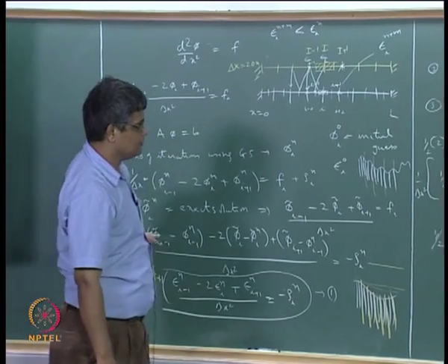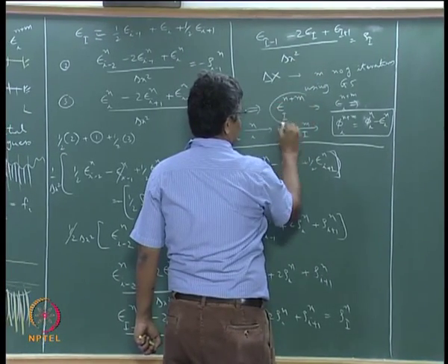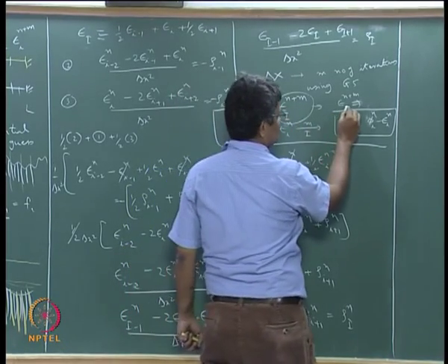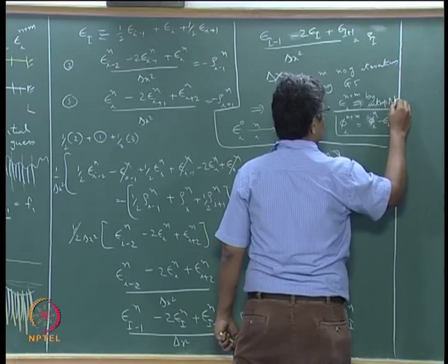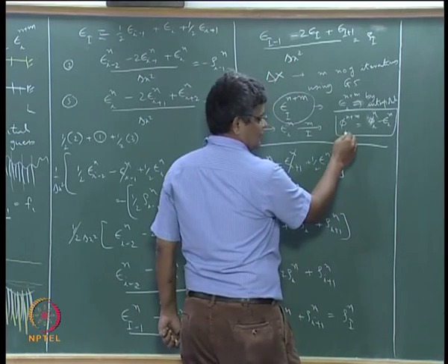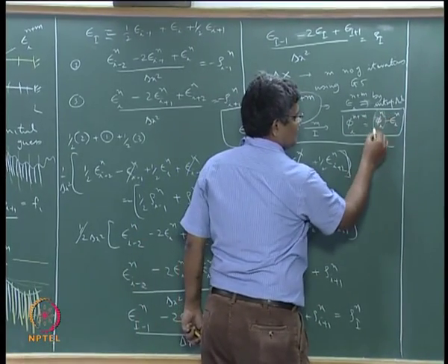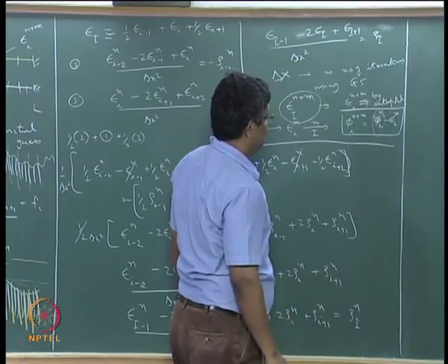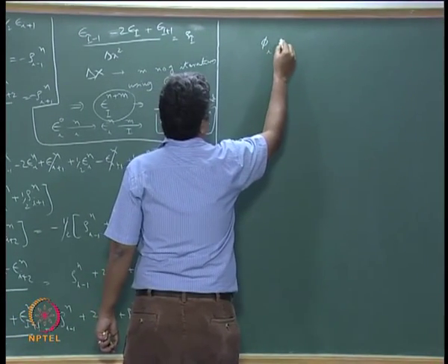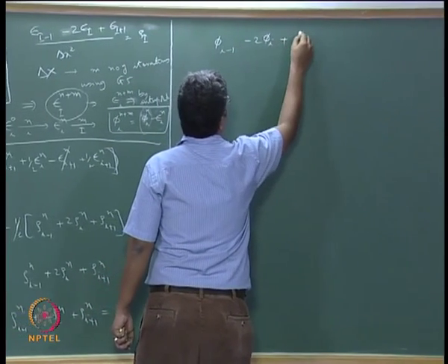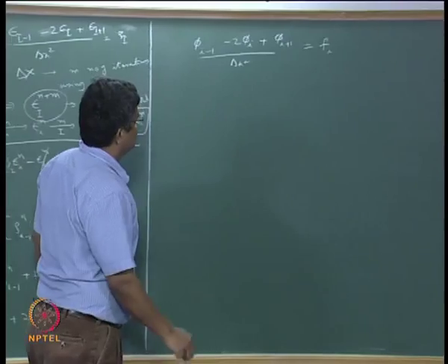Okay, so to summarize here, at the end of this we have the error at each of the coarse grid points. From this we get the error at each of the fine grid points by interpolation. And from this we estimate the value of phi I in this way. This is already computed and this is the error, therefore we get the thing, and then we start again computations. So this is the equation that we have.